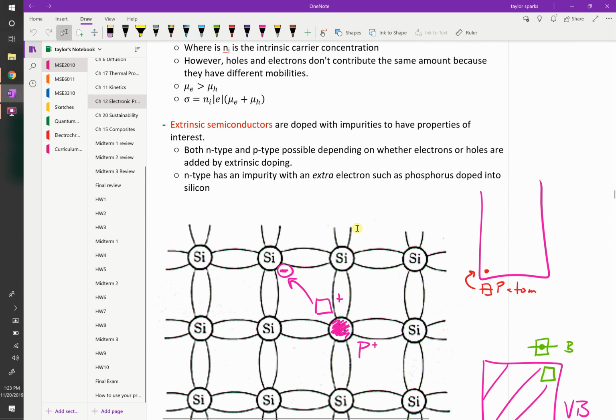So we'll do this one, right? There's a finite number of these phosphorus atoms. You all agree? We dope it to have some number per volume, so there's a fixed amount. And this is a small energy. So we could imagine a temperature at which basically all of these are ionized, but we still don't have enough temperature for these things to start ionizing because it's a much bigger gap.